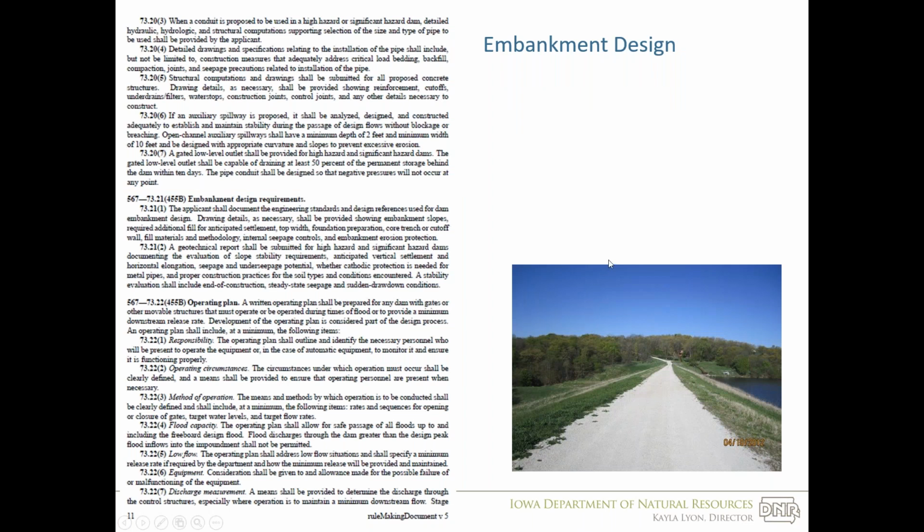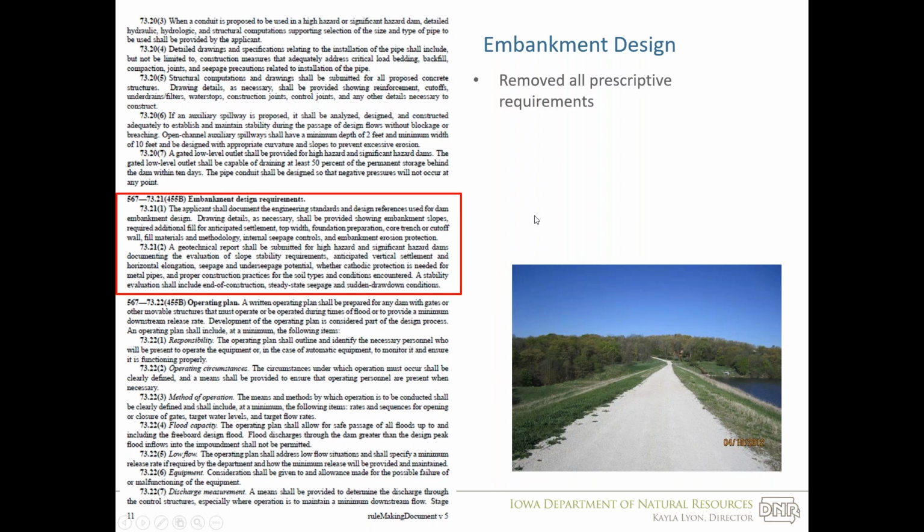Embankment designs, again, we removed all the prescriptive requirements that we had, which was just the top width and the side slopes and the wave erosion berm. But we didn't have any additional embankment design criteria that you could find in TR-60, for instance.